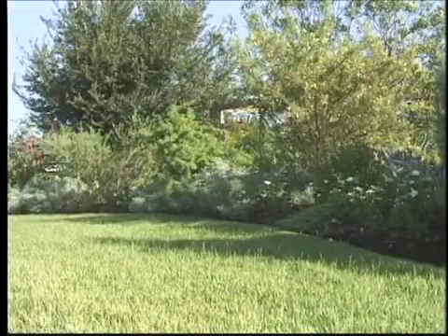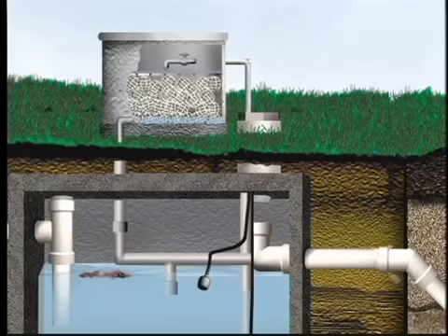The main difference among these filters is the size of the media and the amount of wastewater that can be treated by the media. Media filters are used to aerobically treat the wastewater with microbes growing on the media surface. These filters remove large material, absorb small and dissolved material onto the surface of the media, and this waste material is decomposed by the microbes. Media filters reduce the quantity of organic matter, solids, nutrients, and pathogens.